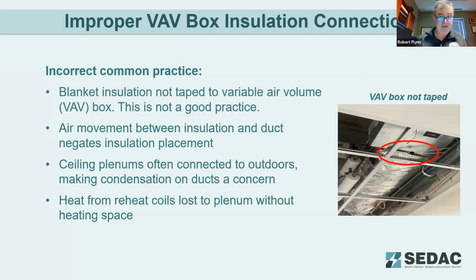A lot of times you'll see when you butt up to it they'll leave the coil itself uninsulated. Back in the field, what I used to do is go right over the coil and leave the uninsulated piping for maintenance open on the VAV box. But you should seal the ductwork to the VAV box as a practice.